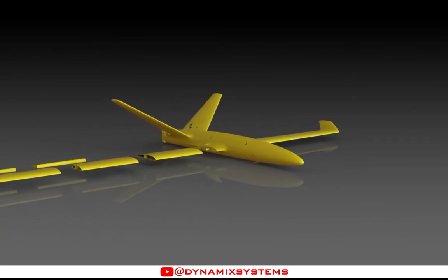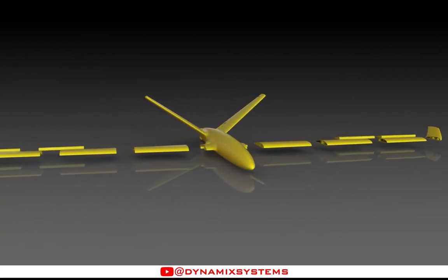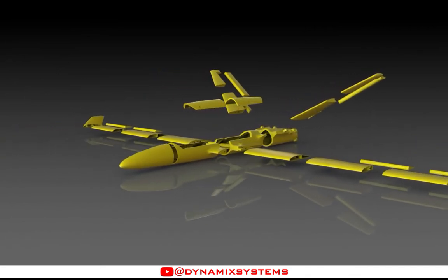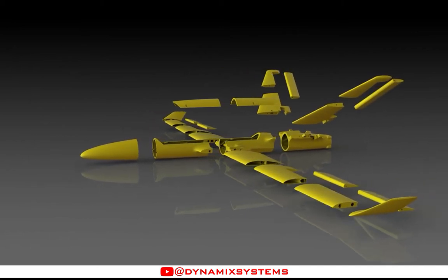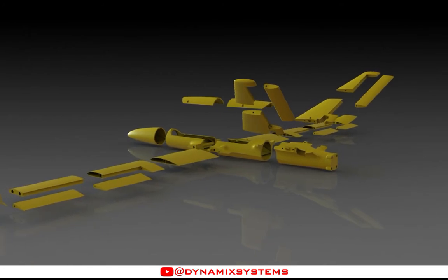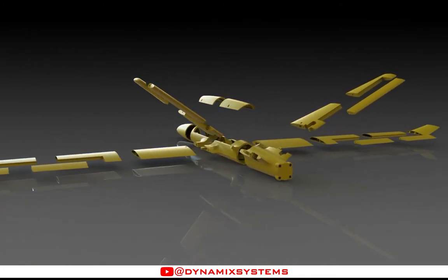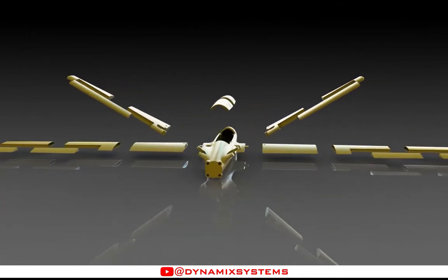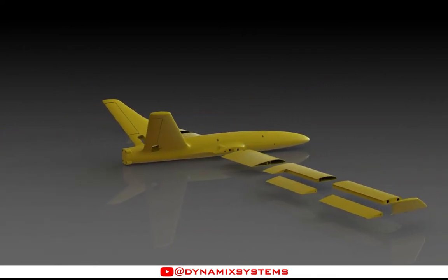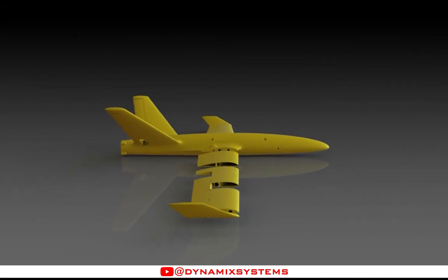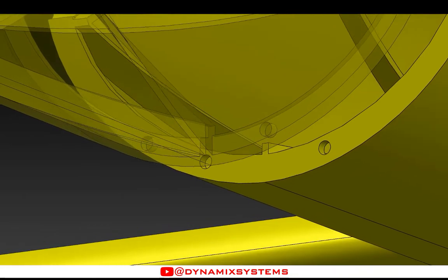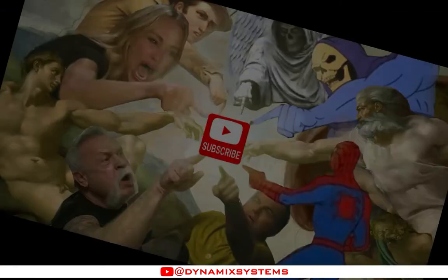After finishing the design, we need to divide the parts into smaller pieces with the proper dimensions for our 3D printer. For example, my 3D printer has a 200 cubic millimeter print volume, so I need to keep all the dimensions of these smaller parts under 200 millimeters. Also, these smaller pieces need some features to get a precise alignment and strong bonds after the print process.